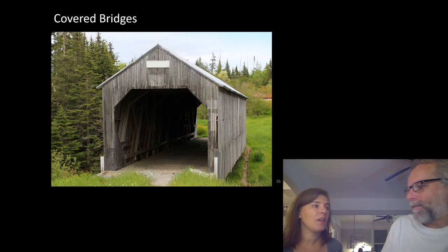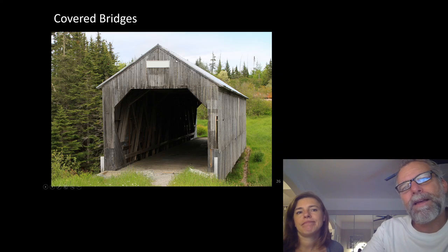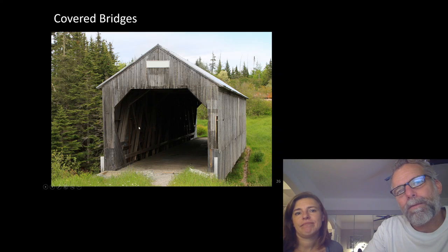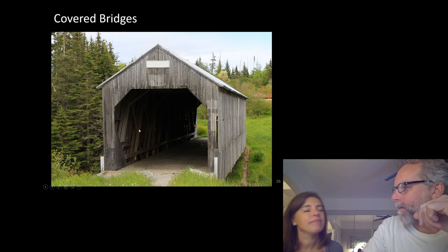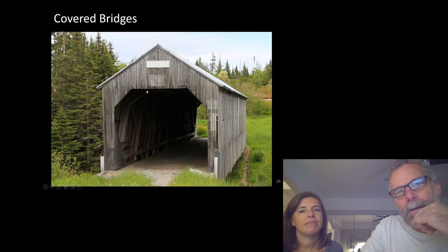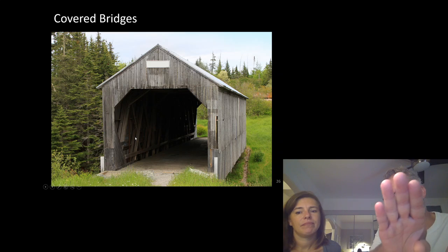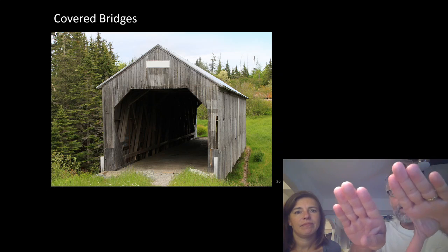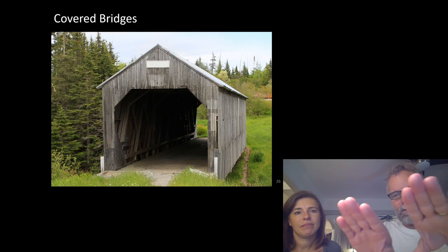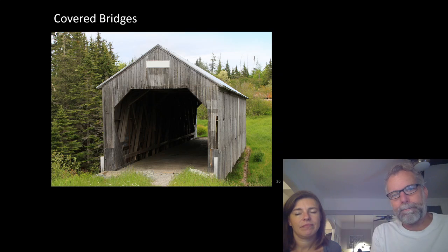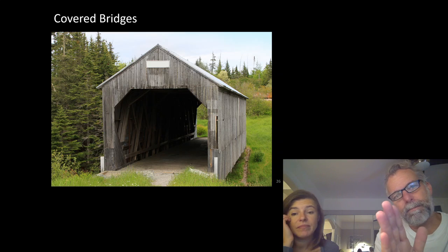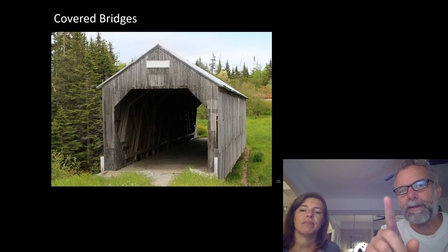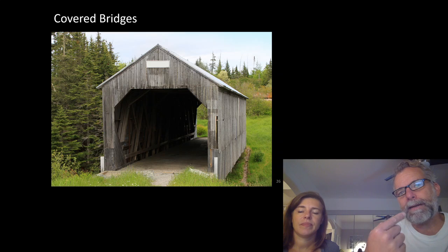So this is a very common truss form for timber trusses. This is the one that I always think of as the Howe truss, but in the diagrams earlier, it looked like the child's truss. The compression elements are double, two side by side, oriented flat this way, so that they're very stable in horizontal buckling. And then the diagonal is also a compression member the other way, helping to resist uplift.